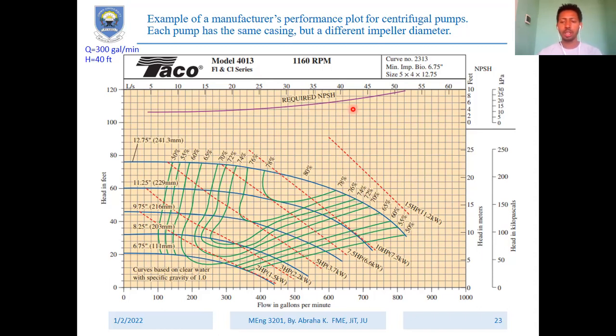Cavitation is the headache in pump design. It is where bubbles form and pitting starts at a location where a low or negative pressure is created. So this purple curve, or the net positive suction head, can be used in calculating where the pump should be placed above the reservoir. That elevation could be determined to avoid the cavitation.